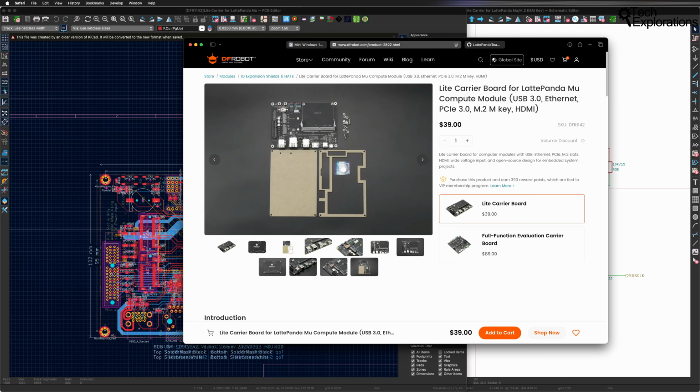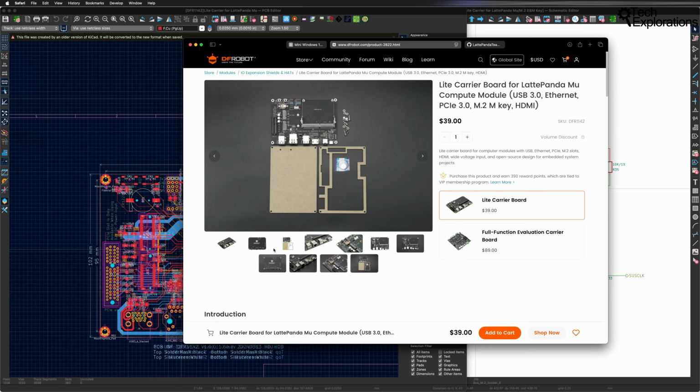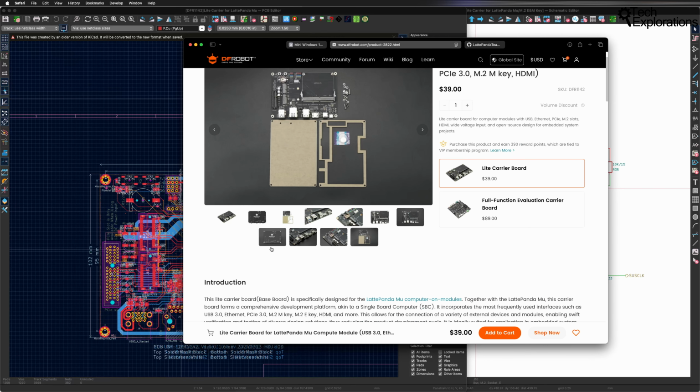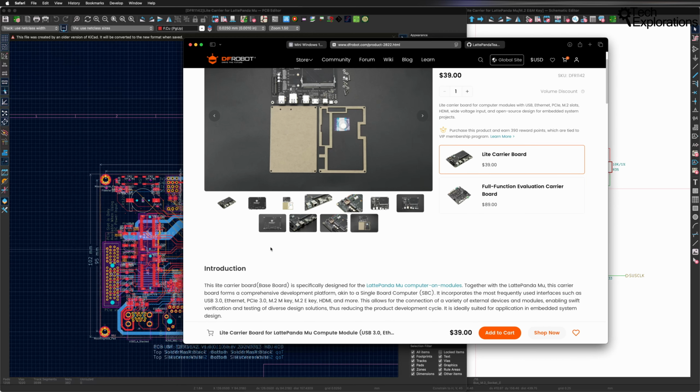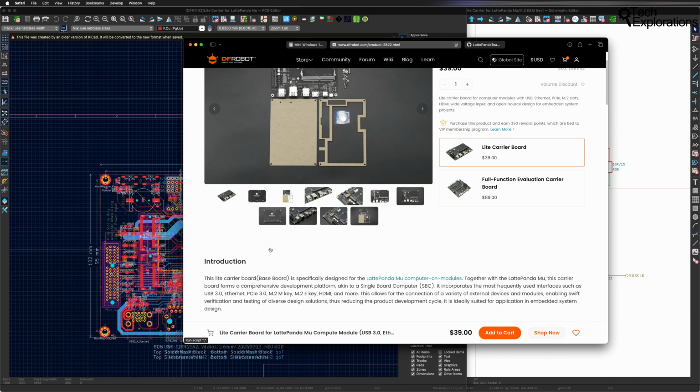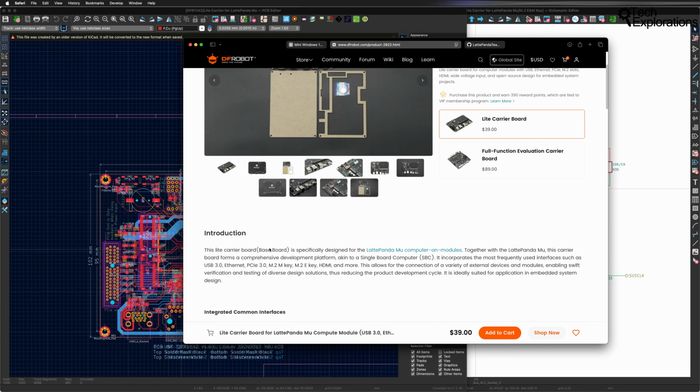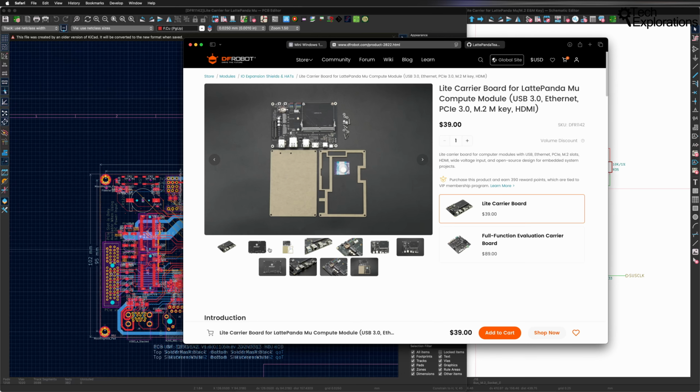If you choose to deviate from a proven reference design, then you're essentially volunteering to repeat all of this expensive validation work yourself. Signal integrity failures, EMC compliance issues, interoperability problems, all can require multiple PCB revisions to resolve, and that turns a straightforward project into a costly nightmare. Personally, I'm not keen to do something like that.